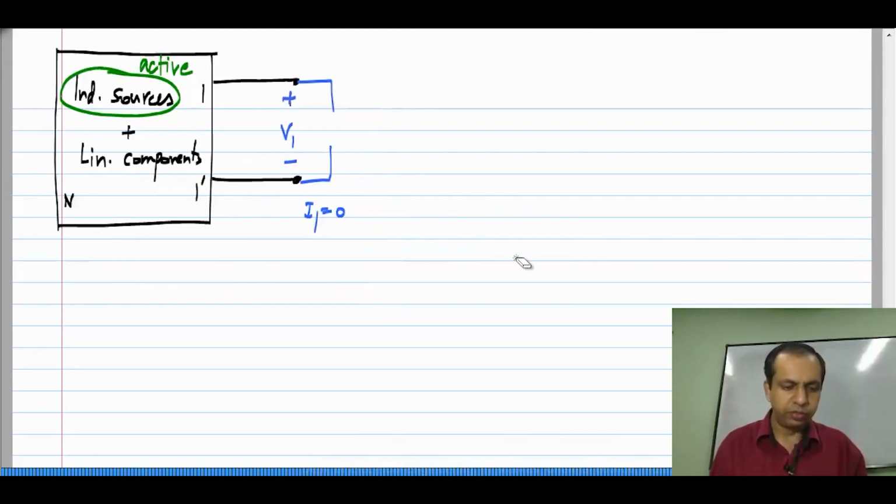This is the case with I 1 equal to 0. Remember, in this case, I am analyzing only this circuit, right. I am not analyzing what is connected to it. This is what makes the derivation independent of the circuit I connect it to. Although, in the intermediate steps, I assume some circuit and that it draws a certain current I 1 and so on, what I am modeling is only this circuit and it is independent of what circuit it is connected to. So, what am I measuring here? I have this circuit N with two terminals exposed, 1 and 1 prime, and I 1 equal to 0.